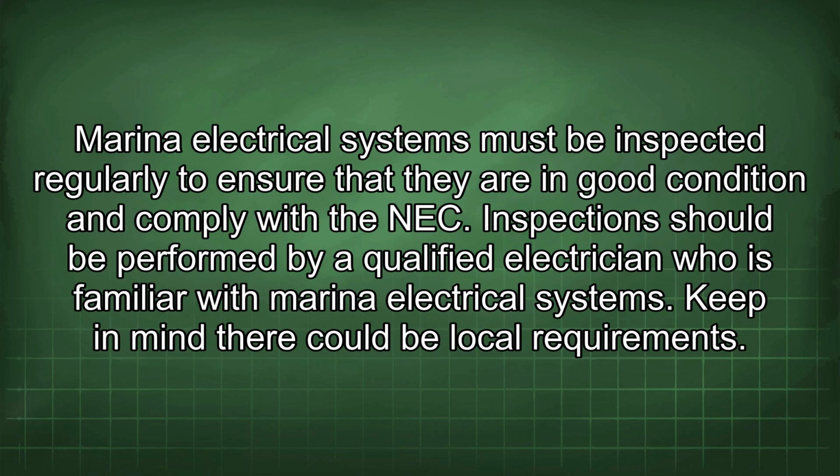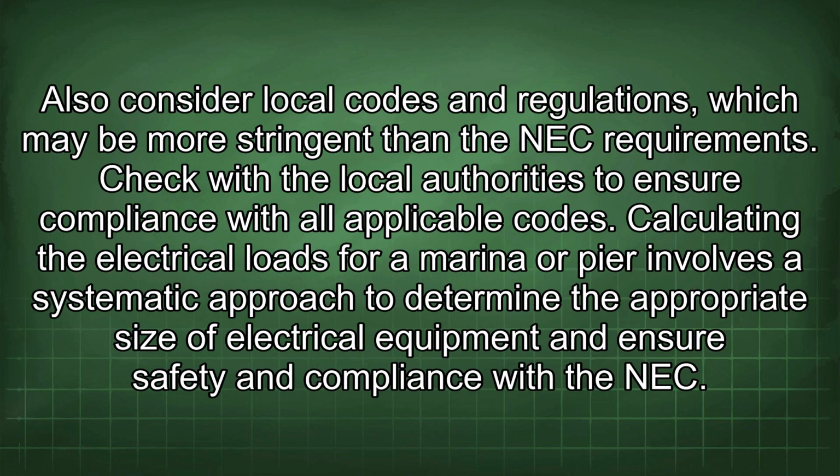Marina electrical systems must be inspected regularly to ensure that they are in good condition and comply with the NEC. Inspection should be performed by a qualified electrician who is familiar with marina electrical systems. Keep in mind there could be local requirements. Also consider local codes and regulations, which may be more stringent than the NEC requirements. Check with the local authorities to ensure compliance with all applicable codes.